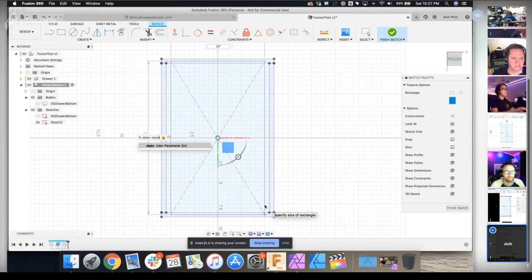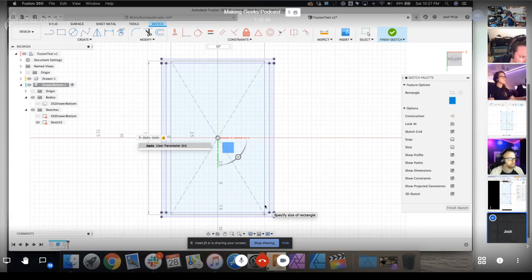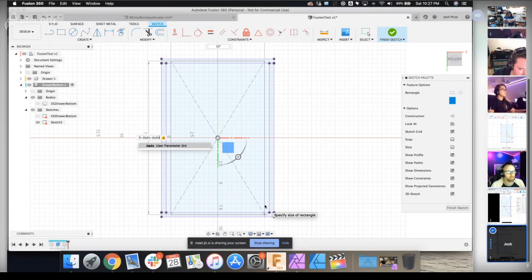Somebody doesn't understand why. I don't know why you subtracted 2 dados. Okay. Be brave. For the front and the back, our dado variable is half the distance of the material. So if I only did one dado, I have a front and a back wall. So that's really half the distance of 2 plywoods. So I need a dado on the front wall and a dado on the back wall. That's why I added 2 dado. Oh, okay. I see.